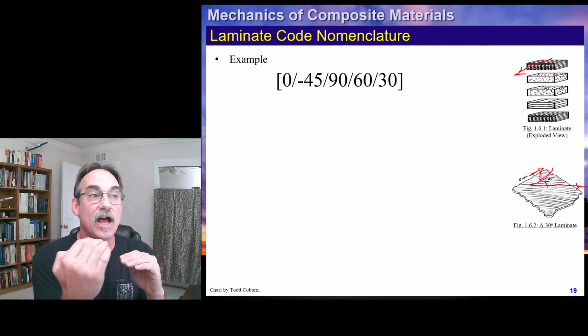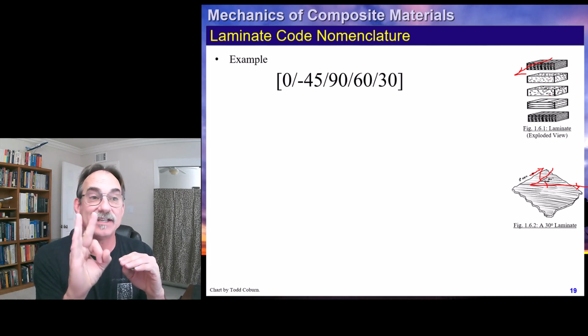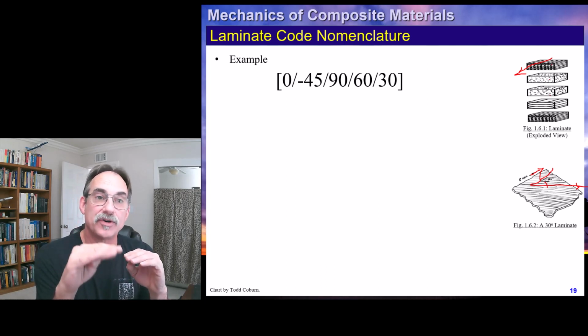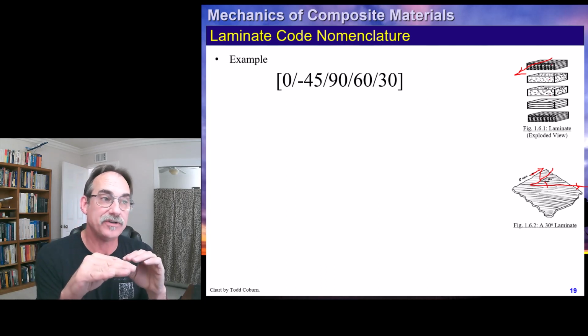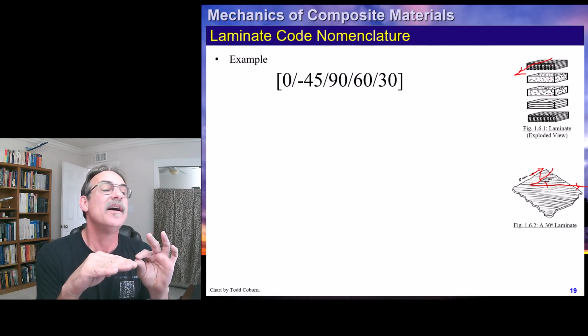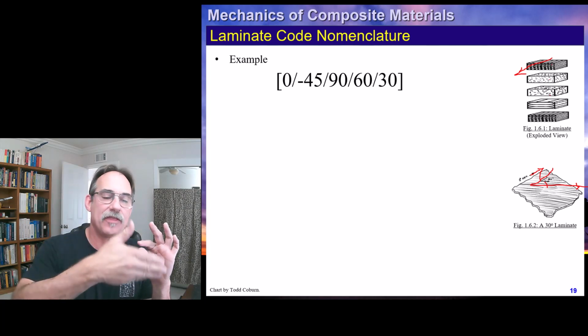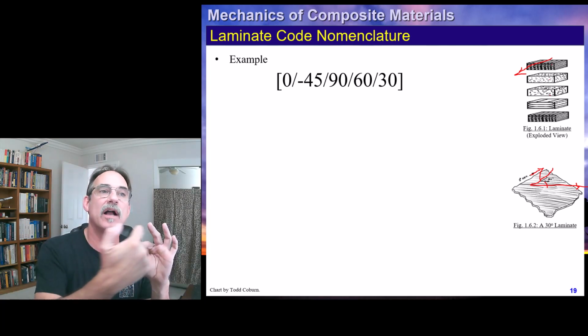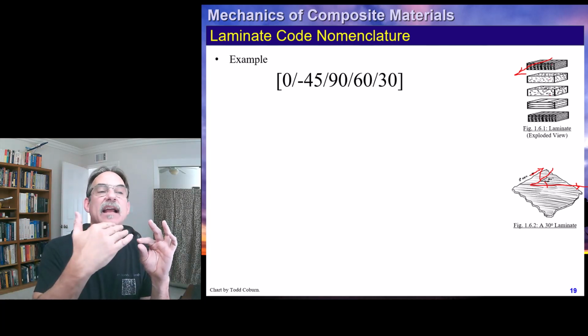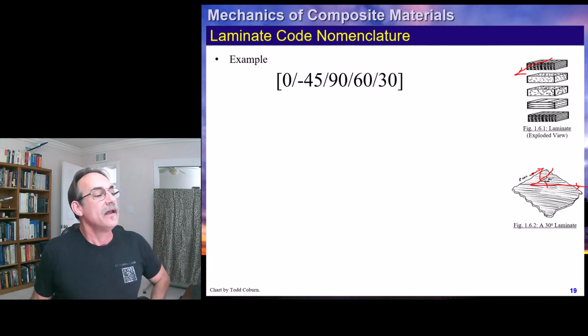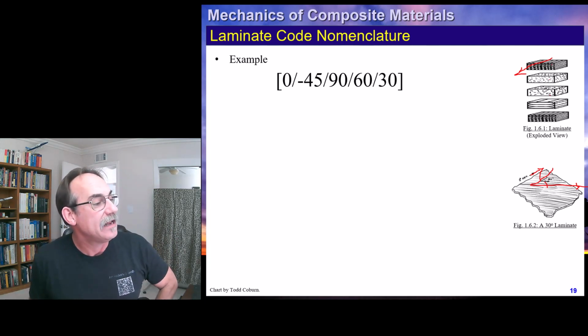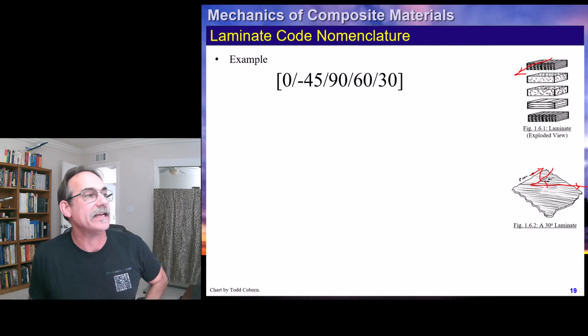If they were going in the longitudinal direction, you'd see a bunch of little ends that are cut off. If they're going in the transverse, right in the 90-degree direction, you'd see the fiber running all along. But if they're at an angle, it cuts through and makes a nice oblong shape, and that's how these look when they're at 45 degrees or something. Anyway, we need to define what each layer's orientation is.